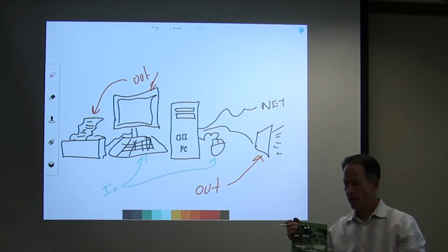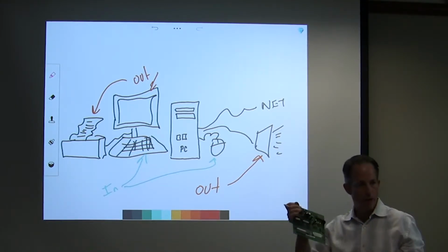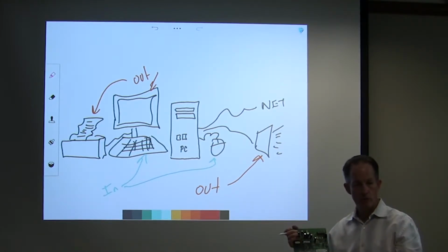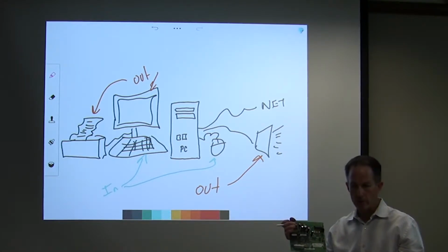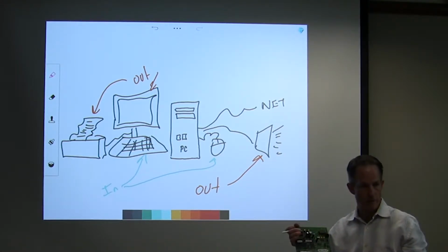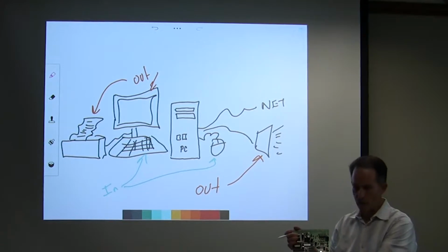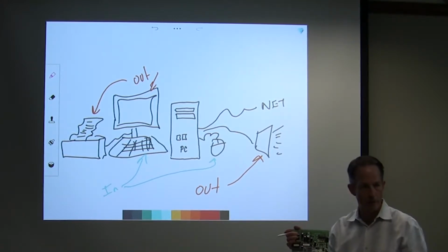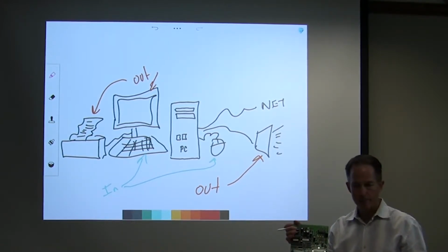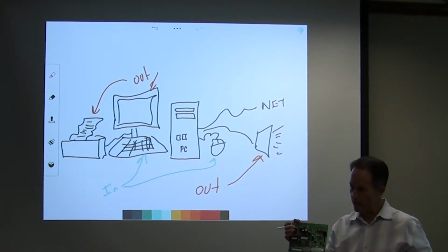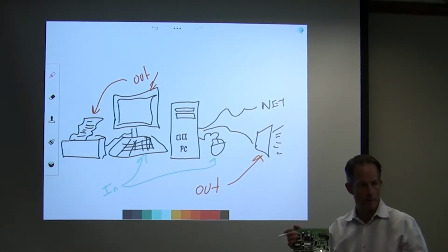Analog. Proportional, up and down. Okay, so they could be up and down analog, 0 to 100. A lot of times we'll see 0 to 10 volts. Sometimes it's a milliamp signal that's then converted through these little components on the boards to a voltage. We have resistive inputs that again kind of turn into a voltage.